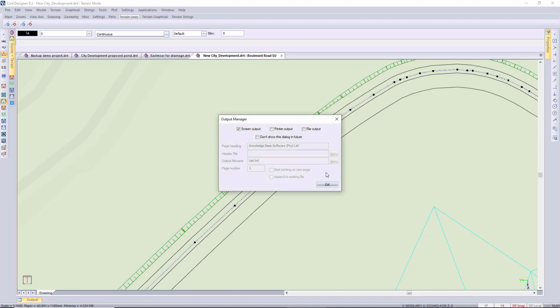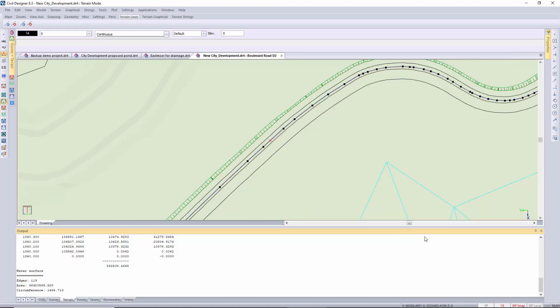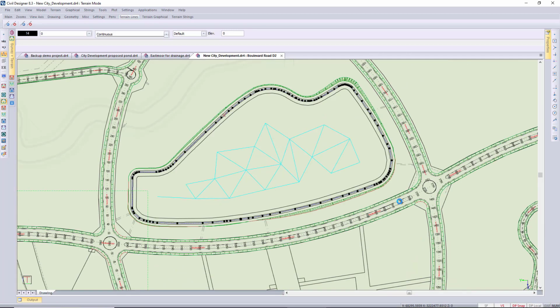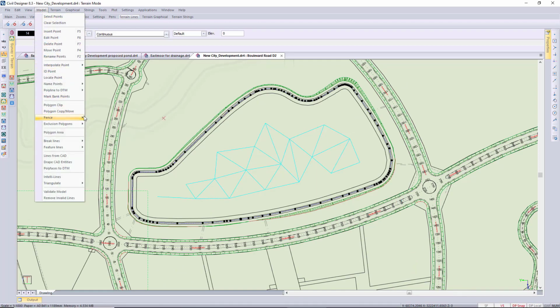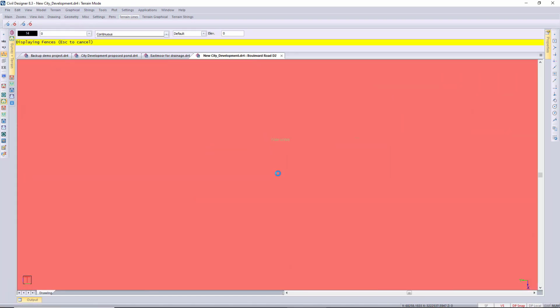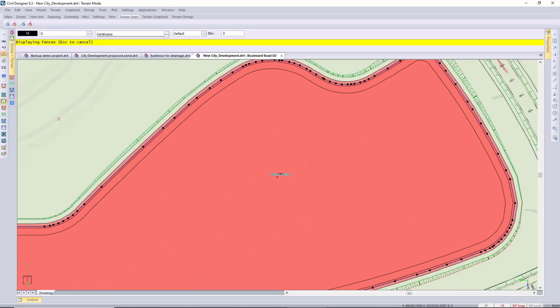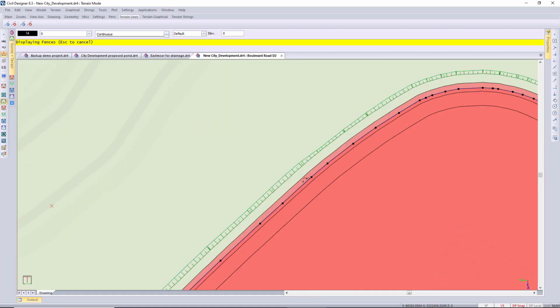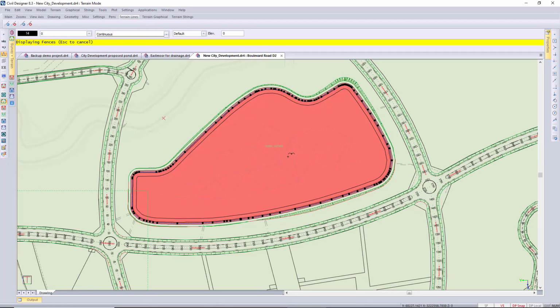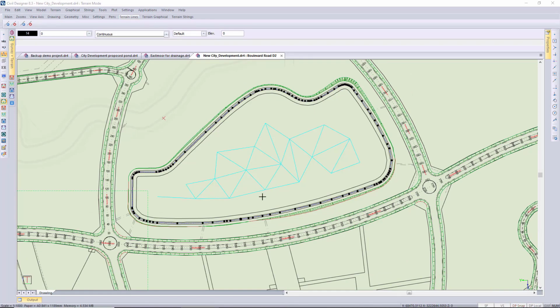Okay, and then you'll see the new fence defined, and we can see in the output window the area and circumference of our new fence, the water level fence. So you can use these fences for various functions, and if you need to manage the fences, it's under model fence. You can delete or remove existing fences, and then you can display all the fences. It does show the water surface, and we've still got the pond fence. You can see if I zoom in here, you'll see the two different shades for the pond and the water surface fences. I can just escape out of there. And then I'm going to move on to the triangulation.